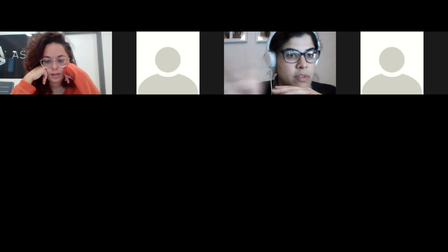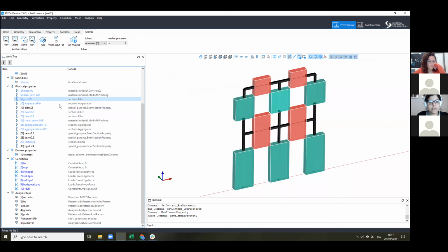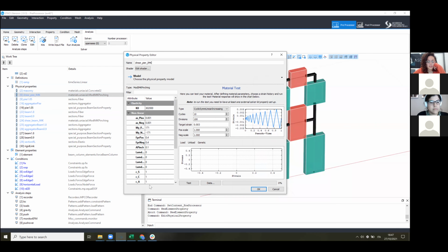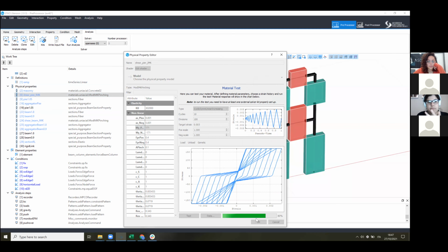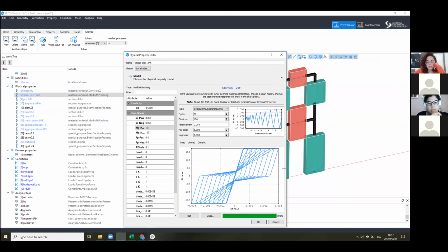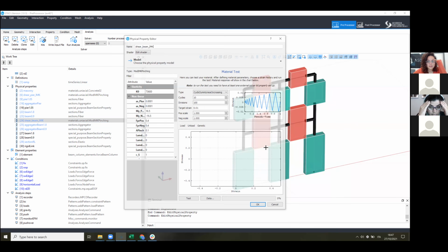Is it the same one? No, it was a different one. There were two uniaxial laws. Even here, there's one for the pier, which has a level of shear of 171 kilonewtons, and it does not really go down because my pier is quite strong. Yes, this is a weak spandrel, strong pier.